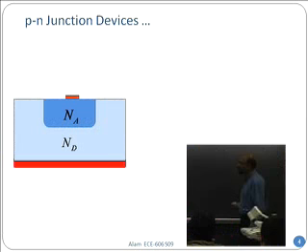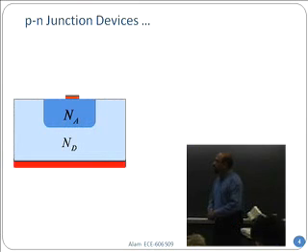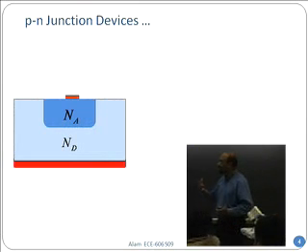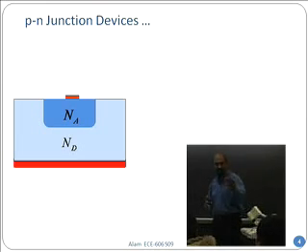So let's get started. A PN junction diode is a semiconductor which has been doped by two different dopants spatially. For example, here in light blue, I show the original semiconductor, let's say it is donor doped. Donor doped means it has a lot of electrons. And then you may have a region with extra acceptor atoms. What are the acceptor atoms? This could be boron, for example, that has been diffused in.